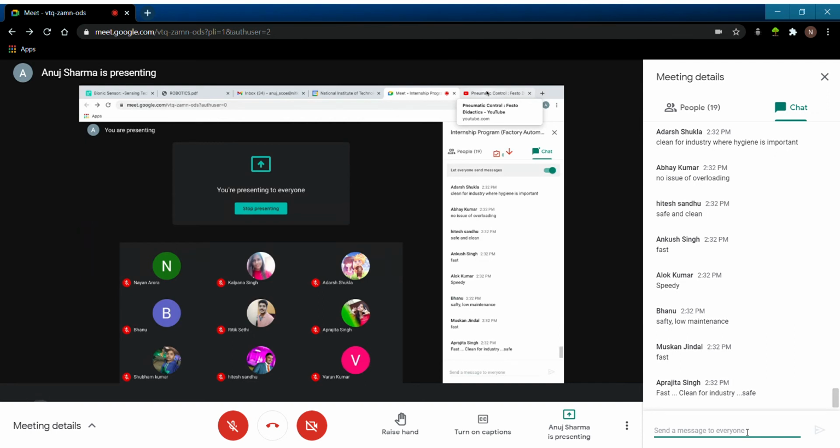So compressed air along with moisture is going to damage your system. This drainage is very important, and during maintenance scheduling this draining is now done automatically. We have a moisture sensor, or you can say level sensor, associated with your compressor, and it gets auto drained. But again, safety is a very important issue, and a lot of technology is involved in this process. This process is now being automated in various industries.